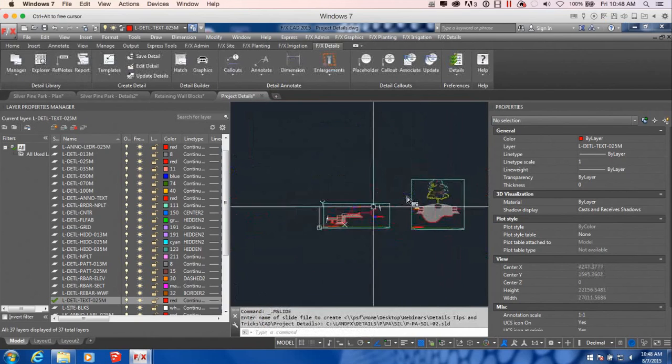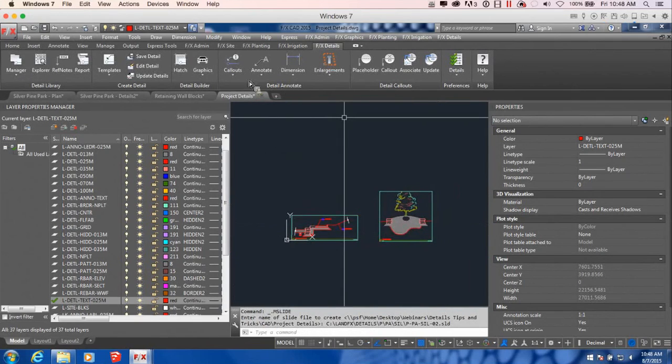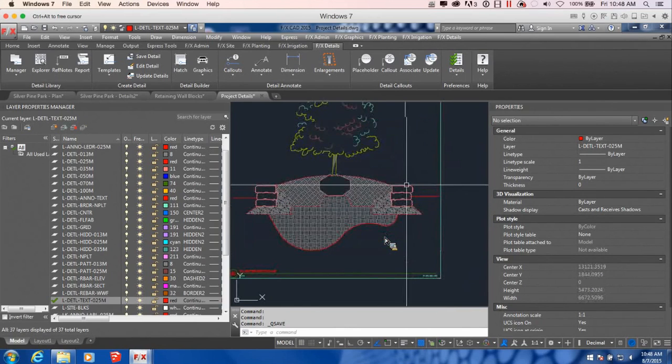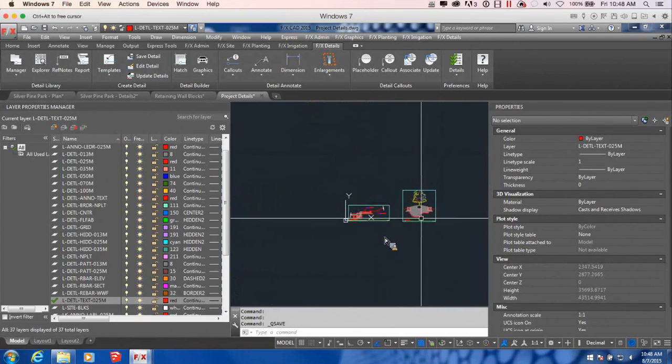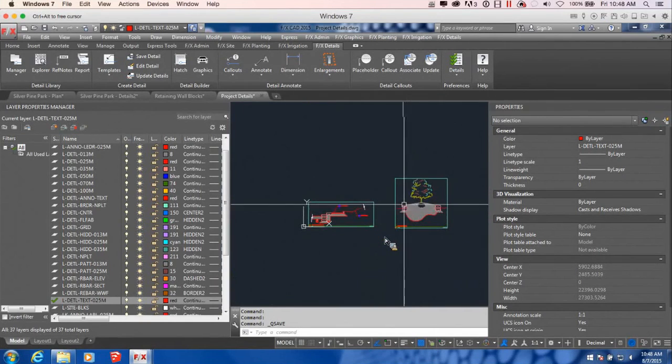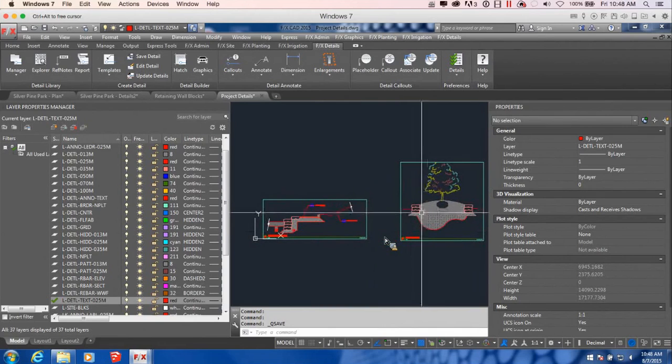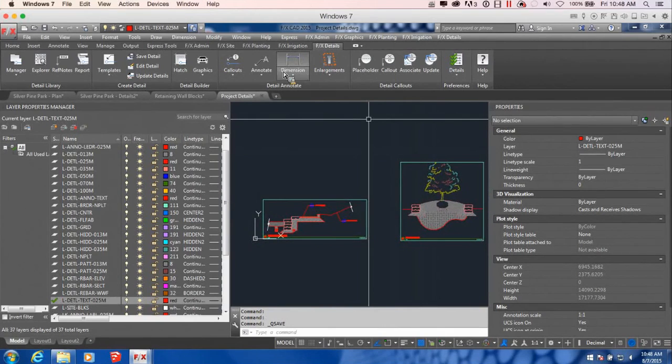Great. Now in the future, I've been saving this all along through the process, saving it into the same folder as the rest of my project. And now if I need to change anything, say make this wall a little higher, I can just come in here, make the changes to this wall, make the changes to that wall. Maybe I'm using a completely different type of wall, so I change out both of these details for a different block for that retaining wall, and then I go ahead to save detail, and I choose this window multiple.